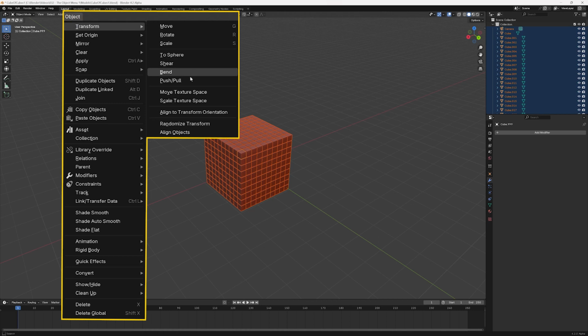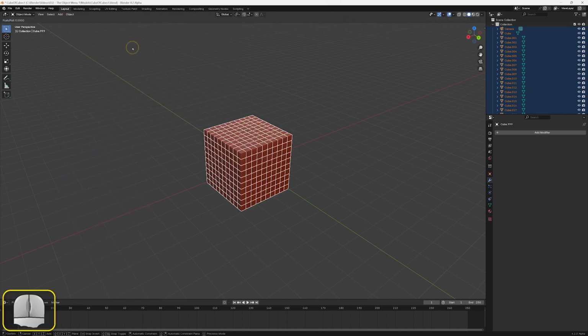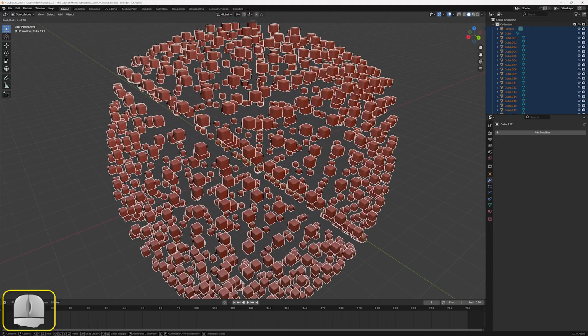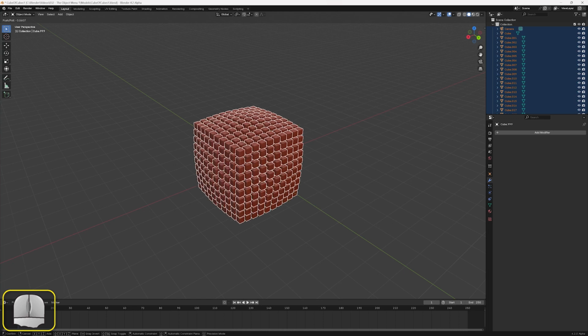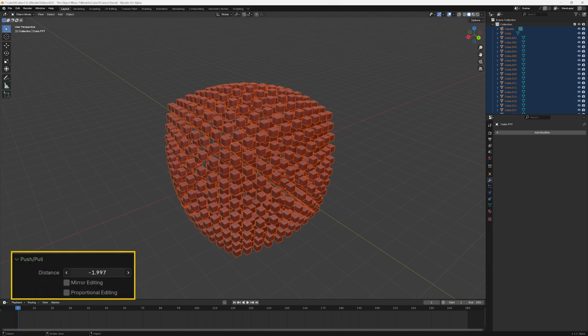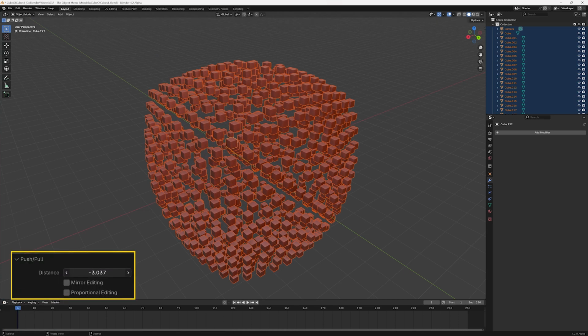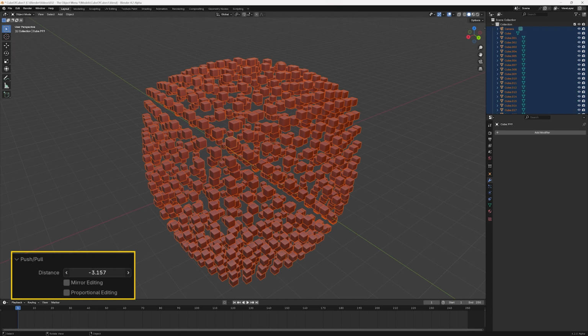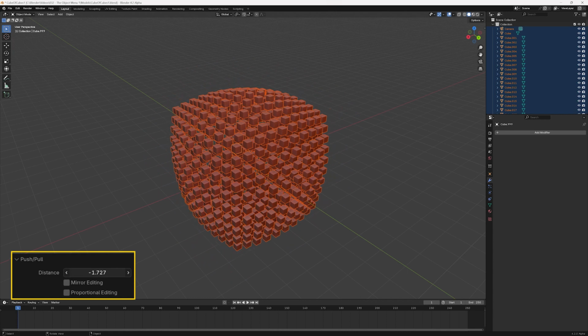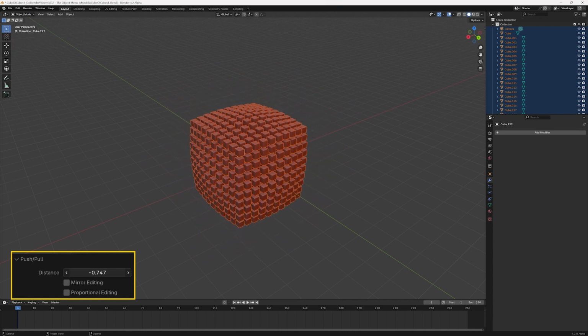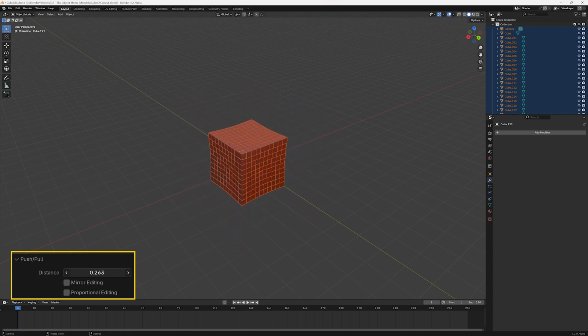Push/Pull moves the selected objects away from or towards a median point. Moving the mouse pointer up or down controls the effect. Left-clicking the mouse completes the operation and brings up the Last Op panel for the operation. Distance determines if the selected objects move outward using negative values, or inwards using positive values. Large enough positive values move the objects out the other side so that we have another form of expansion.